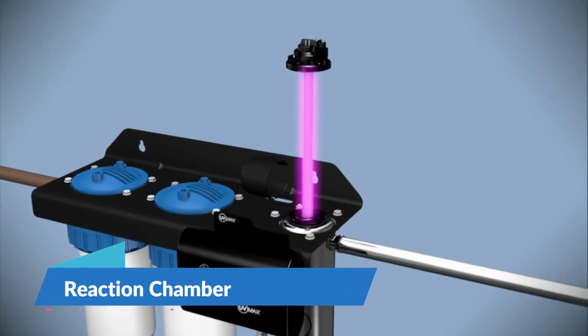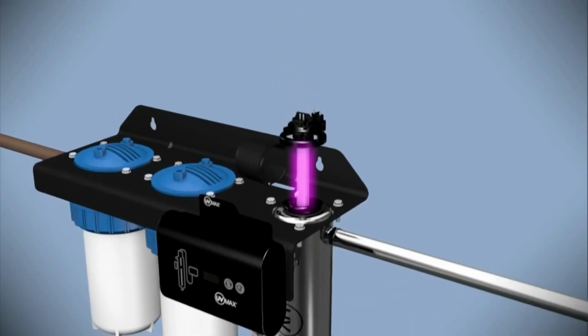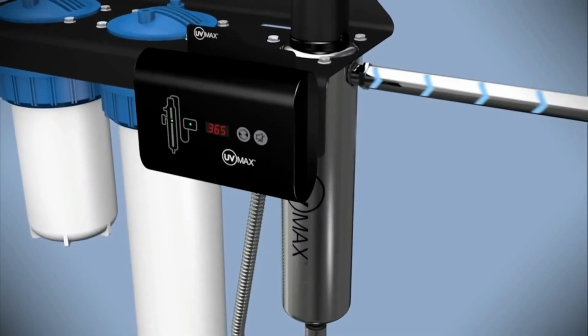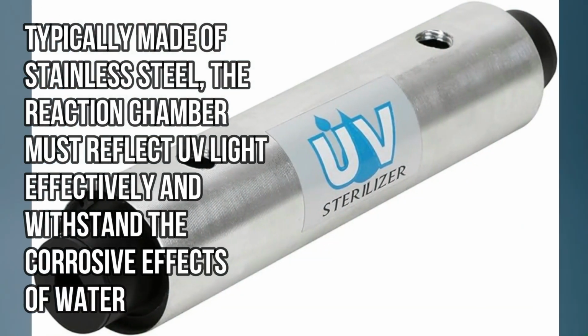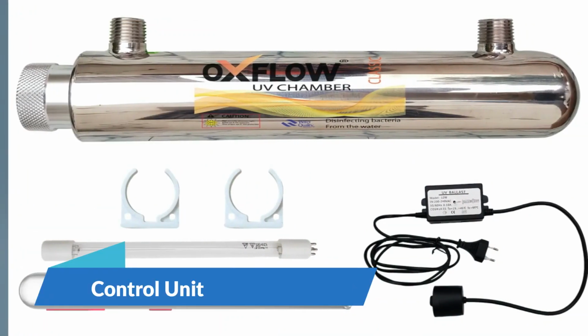3. Reaction chamber. Function. This chamber is where the water is exposed to UV light. It is designed to maximize exposure time to the UV rays while ensuring adequate water flow rate. Design. Typically made of stainless steel, the reaction chamber must reflect UV light effectively and withstand the corrosive effects of water.